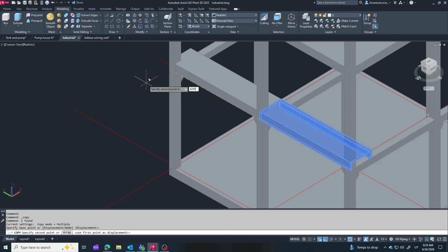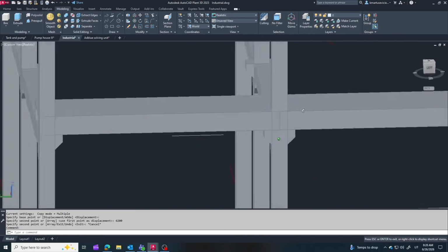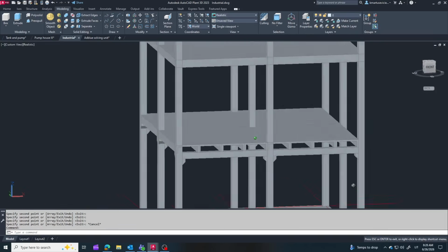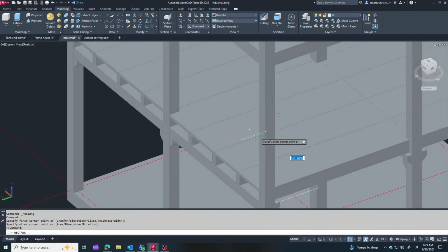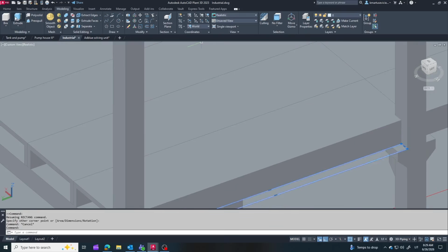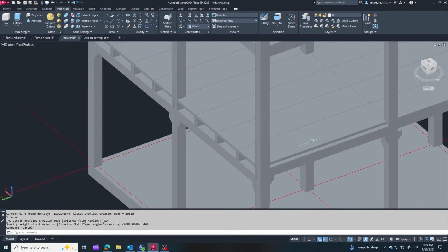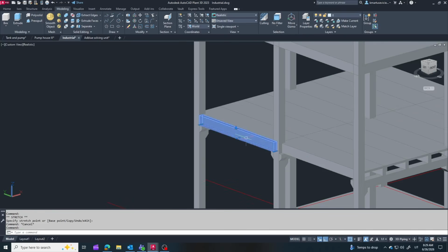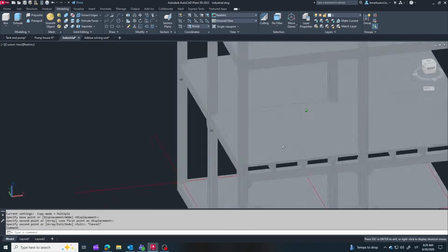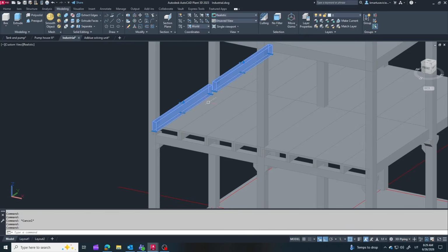If a floor slab is crossed by one or a few pipes, it's common practice to cut circular openings around them, typically leaving about 100 millimeters of clearance on each side. However, if large equipment passes through the floor, a simple opening is usually not enough. In those cases, one or more floor slabs may need to be omitted or replaced with a different structural solution provided by the civil engineer.